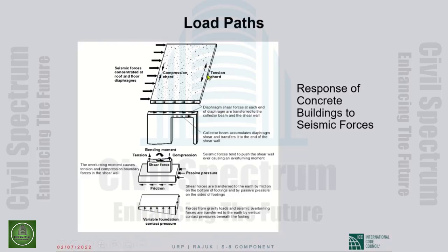Okay, so this picture tells you the concept of the load path. In this case, the inertia forces are going through the diaphragm to the vertical elements of the seismic force resisting system, as we call them, the columns and the shear walls, which take them down to their foundations, and the foundations transfer them to the ground underneath the building.